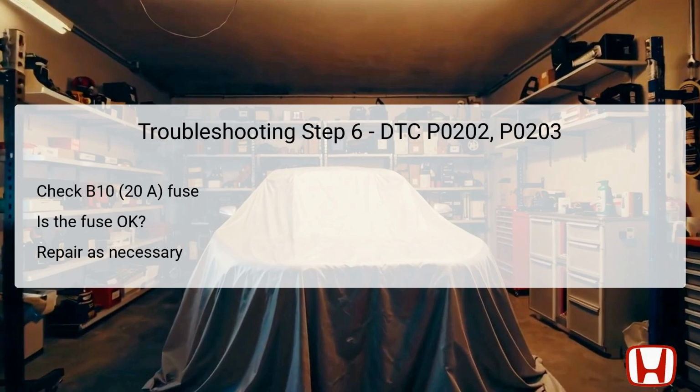Should the fuse be blown, this points to either an overcurrent situation or a short circuit in the wiring, necessitating repairs in the +B-INJ wire segment. Depending on the findings, either repair the wire or replace the fuse, ensuring electrical safety and system functionality going forward.